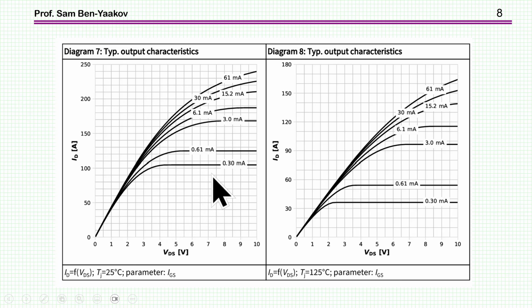It would seem to me that even here, the voltage is controlling the conduction of the channel, but nonetheless, there is a relationship between, of course, the voltage and the current through the characteristic of the diode. So here we have the current of the drain, the voltage drain to source, and the parameter again is the current. Now, as we know, this slope here is the RDS on.